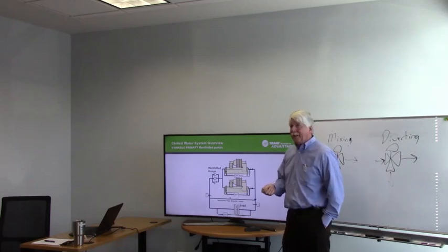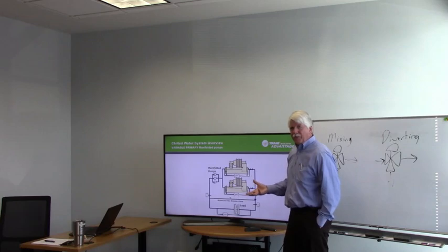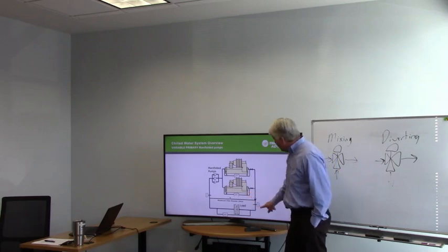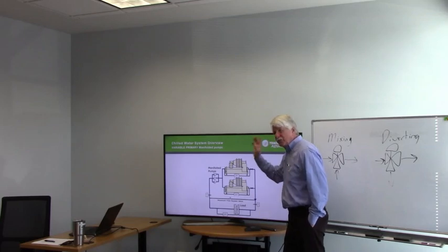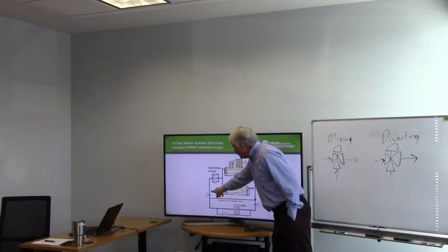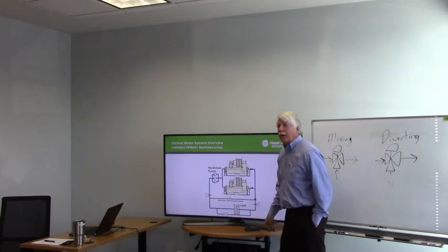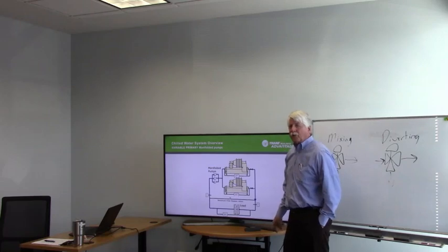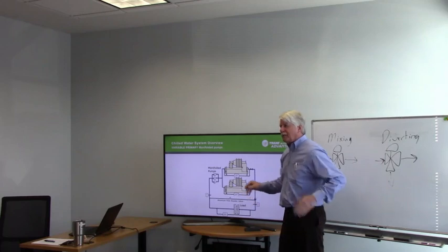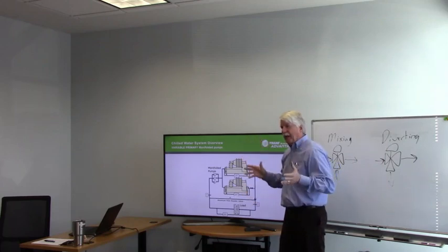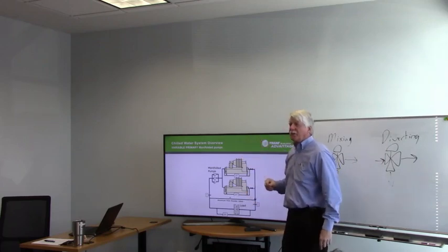And you won't be cooling the system enough. So especially on a primary-secondary system, this sensor always has to be on the far side of the bypass, and the return has to be on the close side of the bypass. If you don't put those in right, chiller plant control won't work because it's not sensing the actual delta T that the system needs.